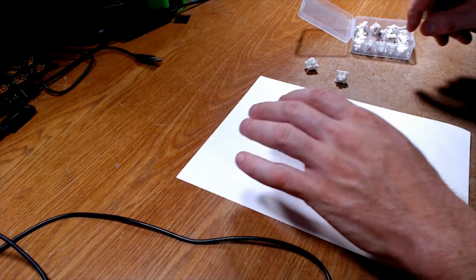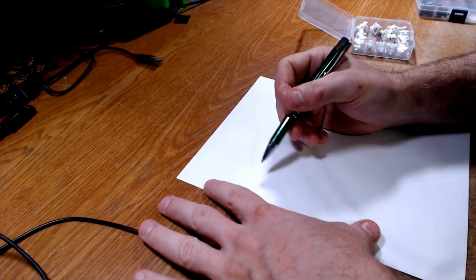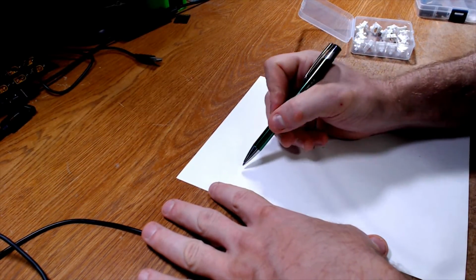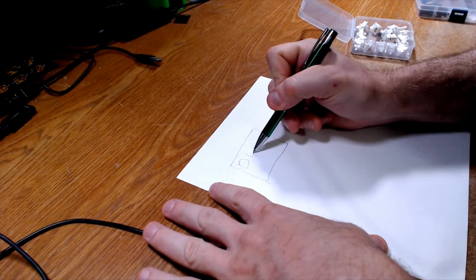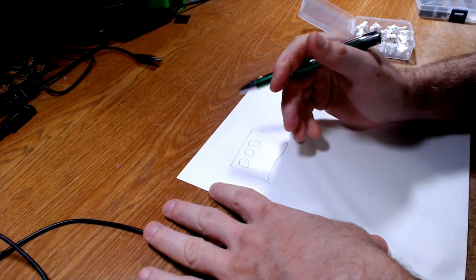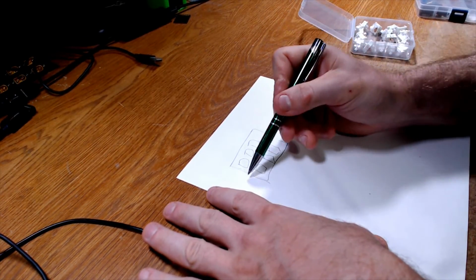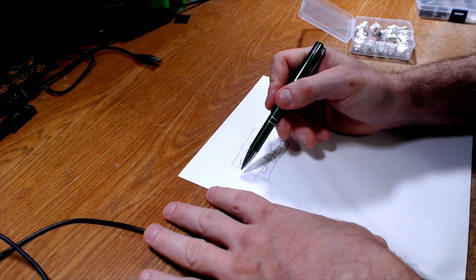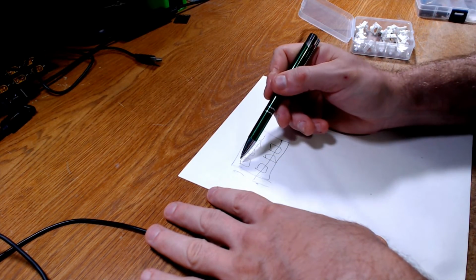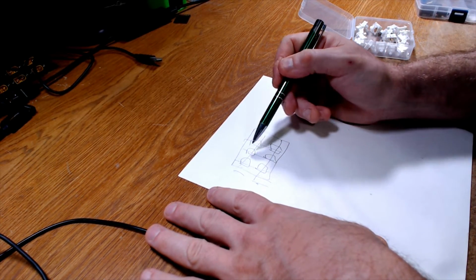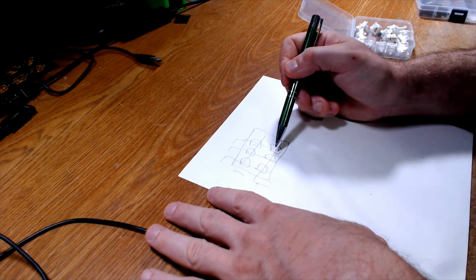So that is, again, the materials we're working with. So let's talk about what we're actually doing, which, again, is why the paper's here. So the plan is very simply an array of buttons. Array of buttons, we're just going to multiplex. So that means that for each row, we have a wire, okay? And then each column. So you can see here, we have 6 wires.